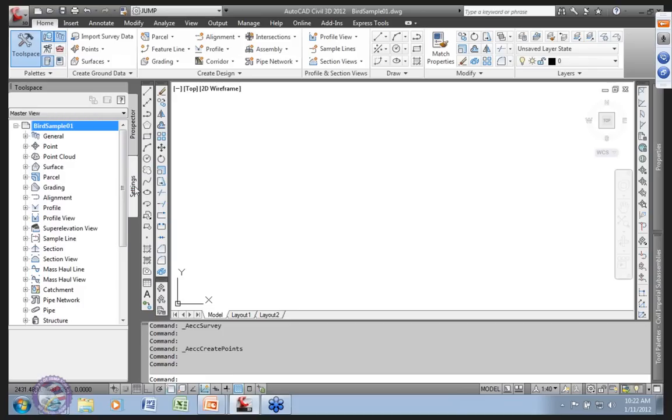Our survey database better be linked up properly with our drawing. Or, for example, I need to take my survey database, which was all gathered in Imperial, and translate it for somebody into UTM. So my drawing can be in a transverse Mercator coordinate system, but my survey database can all be in that 83 Imperial. Okay, so that can do some really cool things. So I can actually produce content via this method in a whole different bunch of contexts for a whole bunch of different customers. So that's one of the goals here.